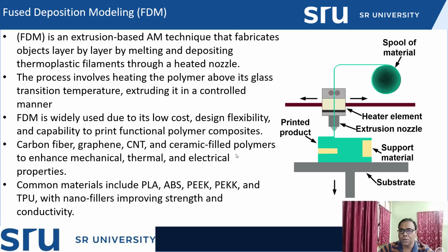So in this fused deposition modeling technique, an extrusion-based technique, can be used for fabrication of an object or any composite material layer by layer, melting and depositing thermoplastic filament through a heated nozzle. So in this, the filament comes from the spool and passes through the heated nozzle, and after that it is extruded from this nozzle, and then it deposits onto whatever the shape and size of the final product desired.